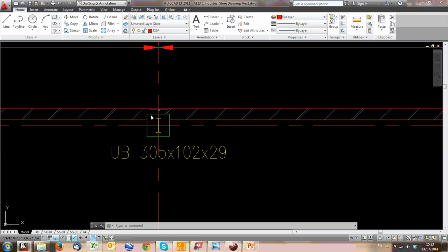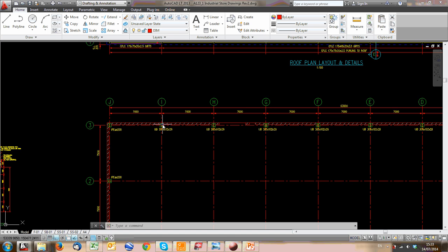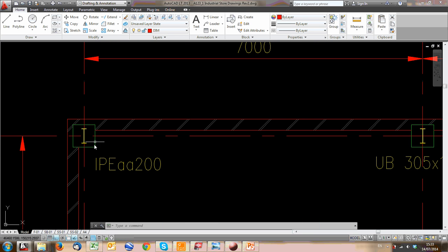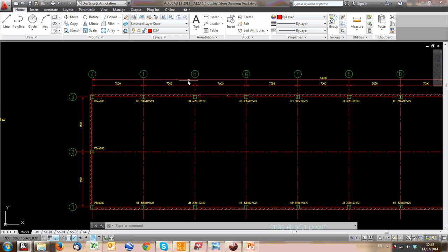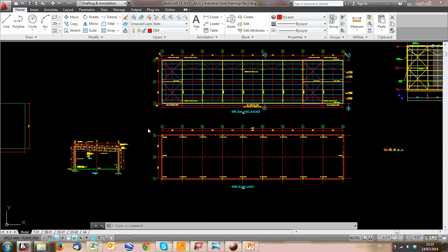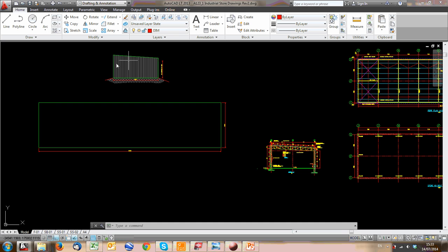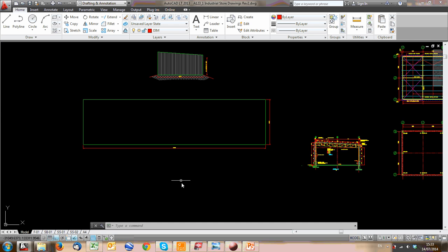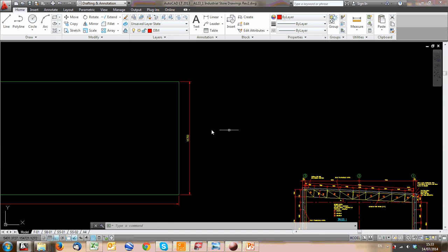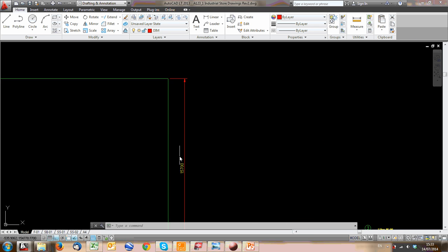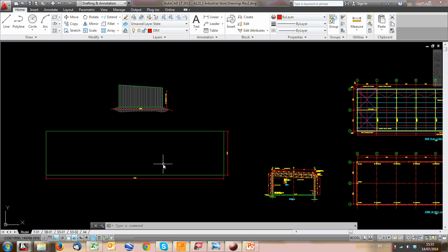Because as you see, the grid line is normally to the center of each column. You need to know where those centers are. Rather than to the edge or the side, you normally put your columns right in the middle of each line, etc. Now, just imagine you got a big block like this from the client, saying, the building must be roughly 63.6 meters by roughly 15.7. He has a space like this on his site which he wants to fit this new